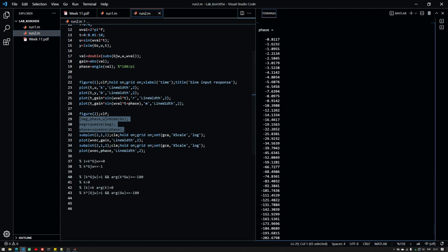Now at this point, here I'm interested in basically this one here, which is not exactly 180 degrees, but approximately 180 degrees. So I will have to search this point, and I will have to search the point here. The same index should be used here, and then that index inverse should give me the P-type controller boundary.